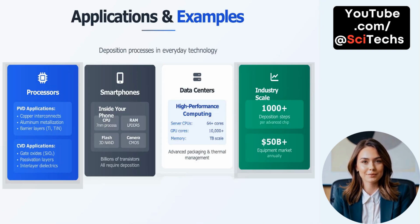Applications and examples. Deposition technologies like PVD and CVD are essential in everyday electronics and large-scale computing. In processors, PVD is used for forming copper interconnects and aluminum metallization, as well as depositing barrier layers such as titanium and titanium nitride. These layers are crucial for electrical conductivity and diffusion prevention. CVD, by contrast, is applied to gate oxides like silicon dioxide, SiO2, as well as to passivation layers and interlayer dielectrics, which ensure insulation and structural integrity.